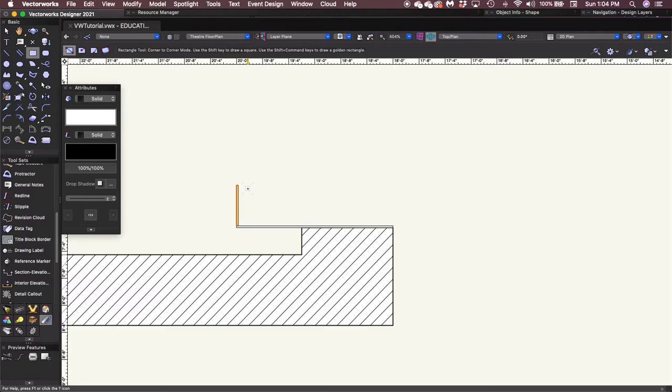Then I'm going to do that one more time in the top right corner. Click and start my rectangle. My delta x is going to be 2 feet, and my delta y is going to be, again, minus 1/4, because I've got a 1/4 inch piece of plate steel. And I'll hit enter and click to finish it. And so now I've created my smoke pocket.